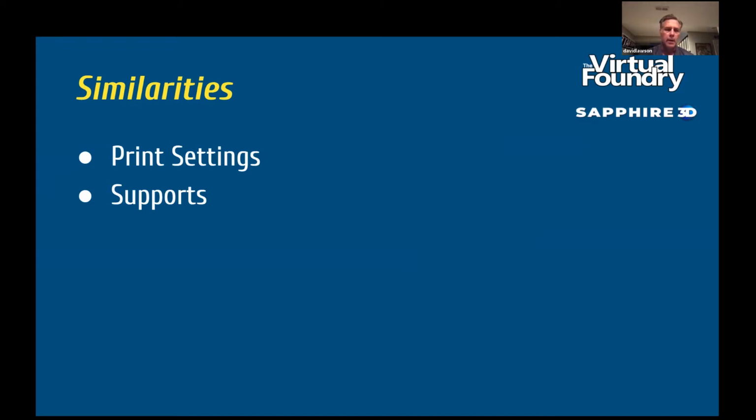And then the other thing typically will be the support material. Like you indicate there, Filamet is great support material. I've experimented a little bit where I might have certain layers or a raft or anything like that where I'll use PLA and then switch to Filamet. But in general, I like it as a support material as well if you don't have a ton of support, because then it just easily comes off.